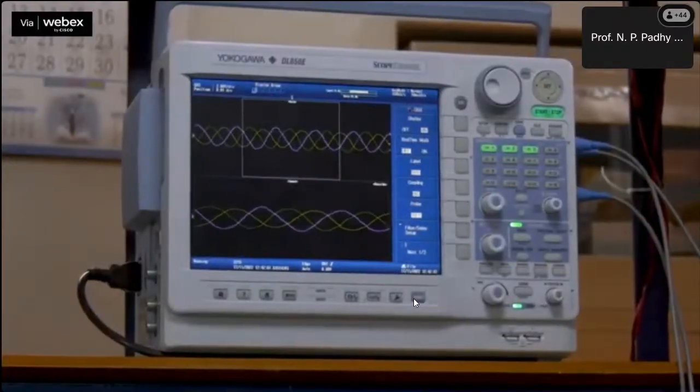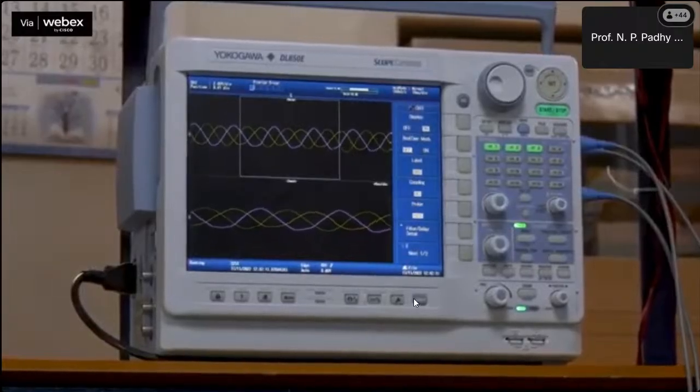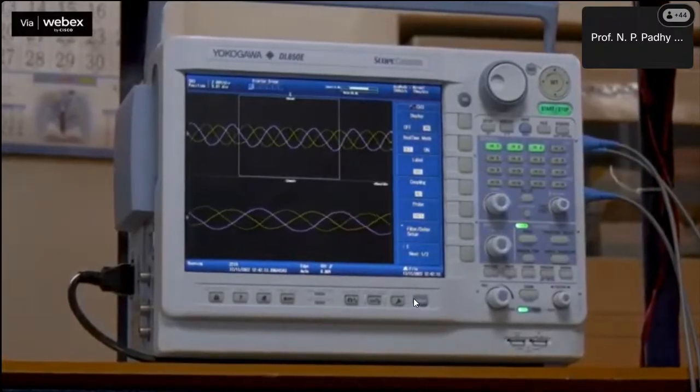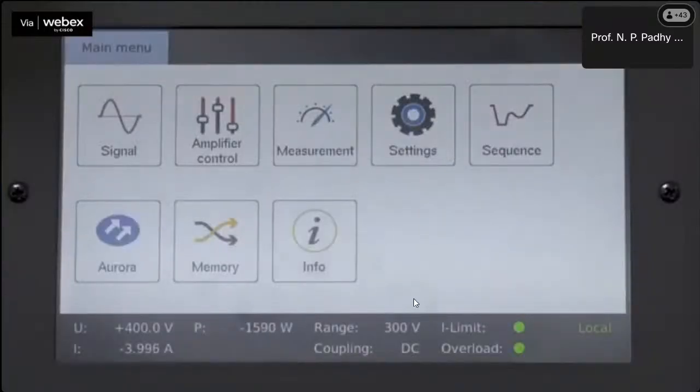By looking at the DSO, we can observe the increase in the DC load reflects the current magnitude. Looking at the power amplifier power sign, which is negative, means the power is flowing from the AC grid to the DC bus. So, earlier it was DC to AC grid and now it is AC grid to DC bus. The DC bus voltage is always regulated to 400 volts.